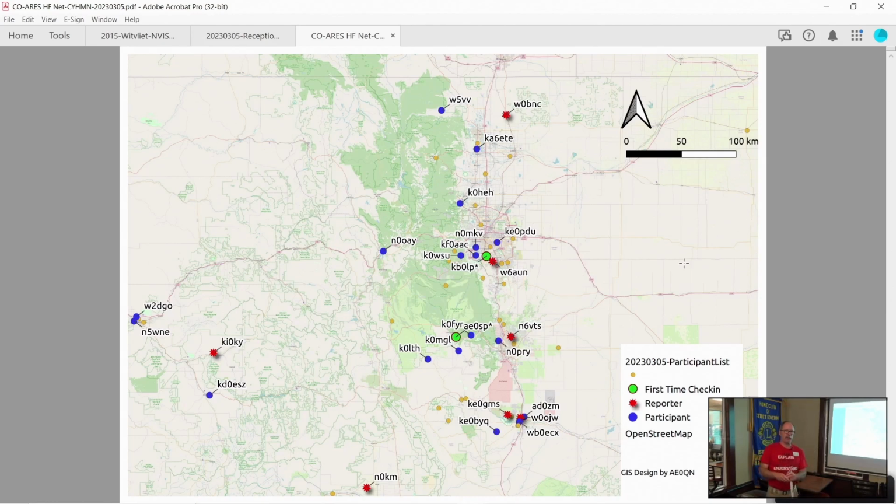And I found out on an end-fed random, although you can tune a wire that's less than a quarter wavelength long, that's where it gets finicky. So I went with more than a quarter wave on each of those 3 bands, which is why I'm using the 72-foot wire.